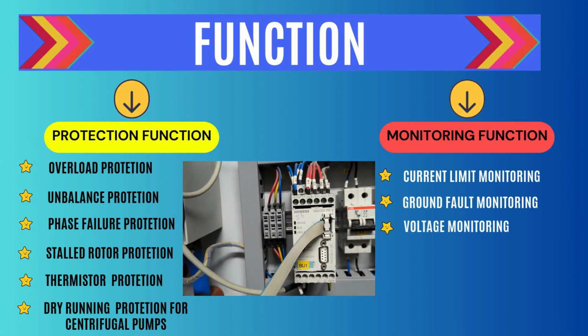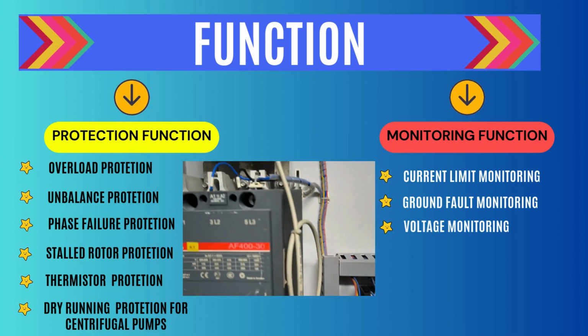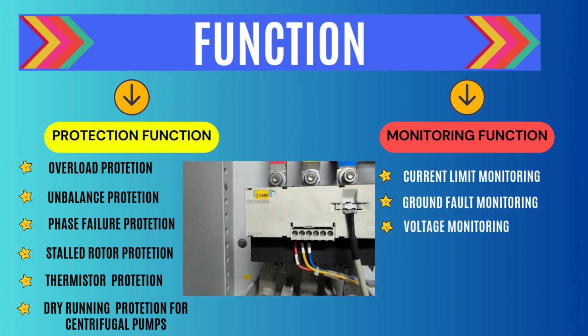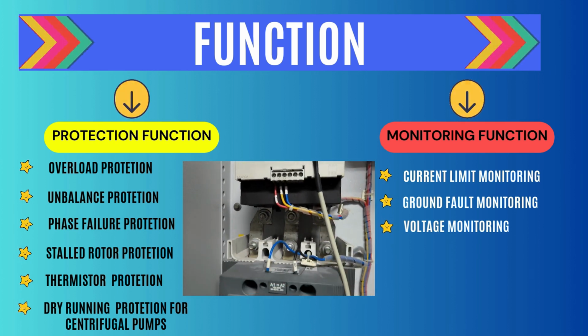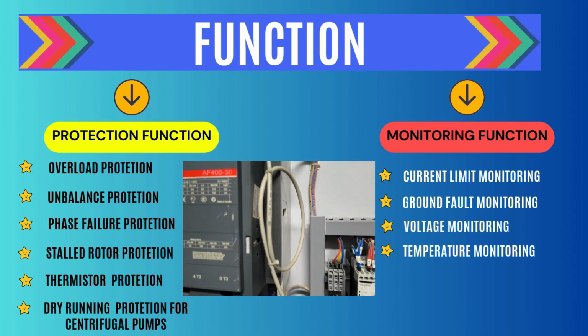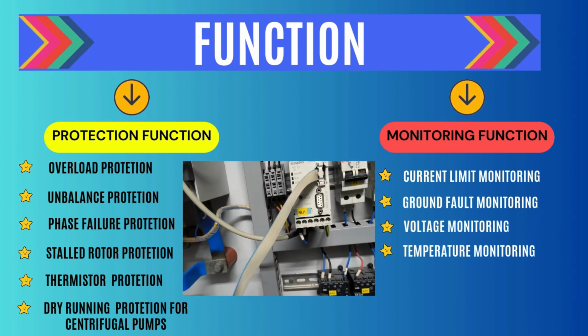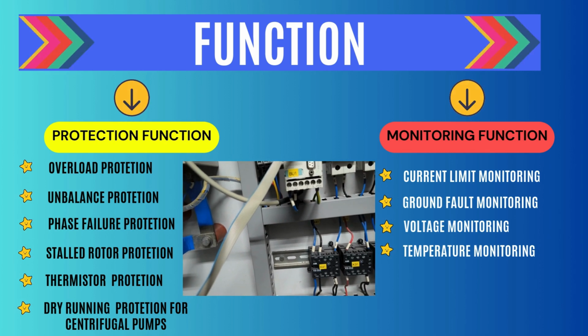Temperature monitoring. The Simocode Pro S, Pro V and Pro V Profinet GP devices have the option of implementing analog temperature monitoring, for example of motor winding or bearing. Simocode Pro S with a multifunction module, Pro V or Pro V Profinet with the temperature module. Active power monitoring.